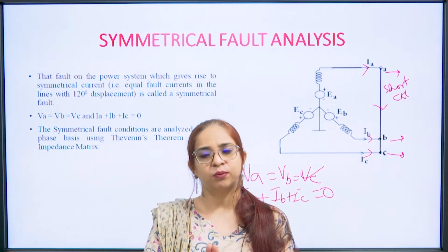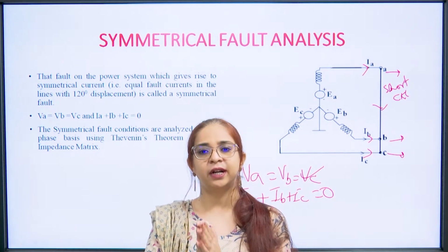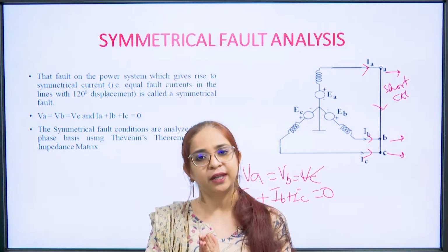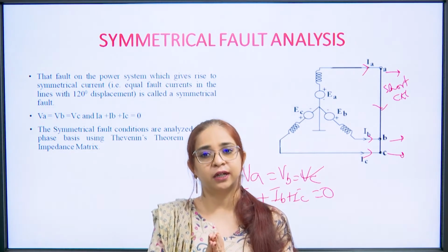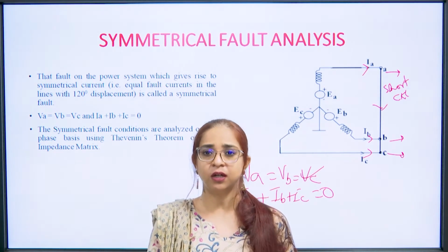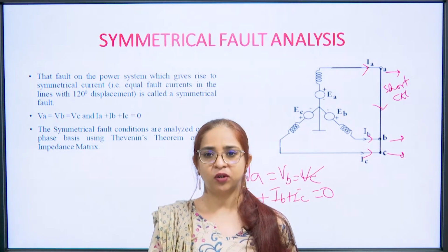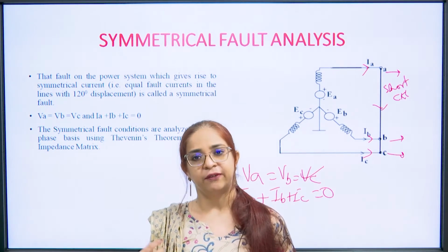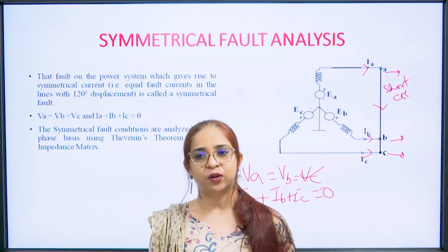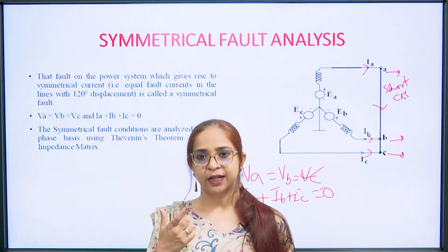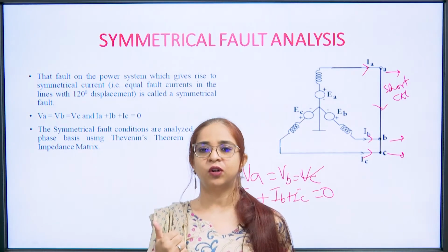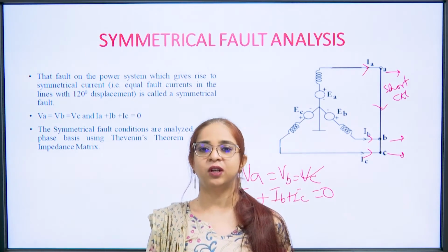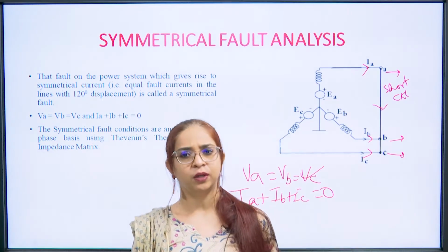जैसे Thevenin theorem को अप्लाई करके हम कहीं लोड करंट की वैल्यू निकालते थे, सिमिलरली यहाँ भी सर्किट, इक्विवेलेंट सर्किट अगर डिड्यूस हो जाए, जो कि कैसे डिड्यूस होगा? रिएक्टेंस डायग्राम के थ्रू, विच वी हैव ऑलरेडी कवर्ड इन द प्रीवियस लेक्चर. It will get deduced from there, we will draw the reactance diagram per phase. What next? We can determine the value of fault current by applying Thevenin's theorem quickly.